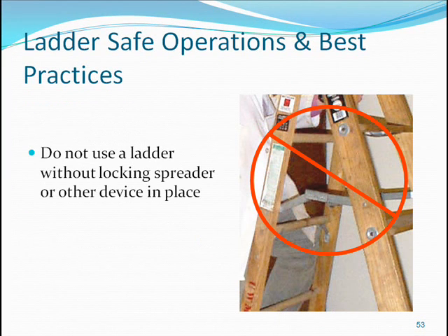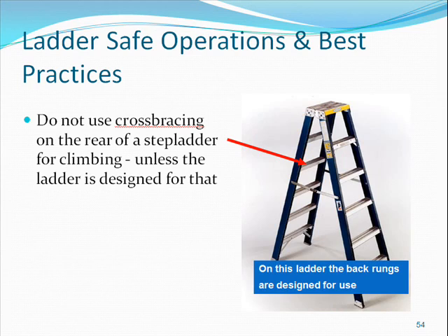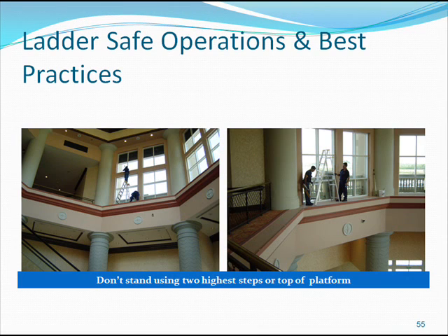Do not use a ladder without the locking spanner or other device in place. Do not use the crossbar or rear of a step ladder for climbing unless the ladder is designed for that. On this ladder in the photo, the back rungs are designed for use. Do not stand on the two highest steps or the top of the platform.